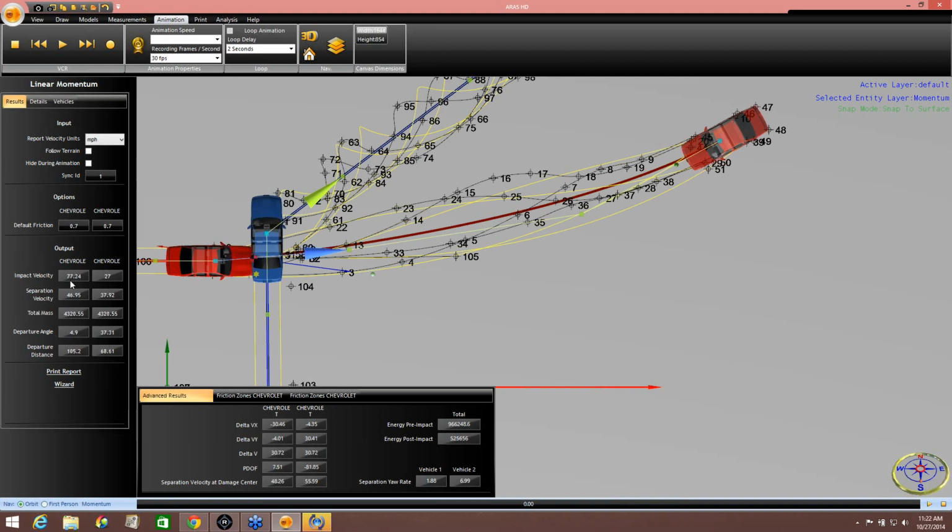So this is the most important and probably most difficult part of any momentum calculation to get right. What did the cars do? And this is where everybody's going to have their own opinion. This is the place you'll get attacked, whether you do this by hand, whether you use a tool, whatever. Because I can assign whatever friction I want there to get whatever speed I want, really. I could do that.